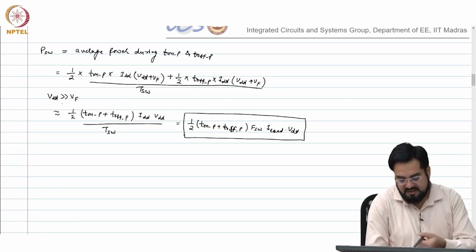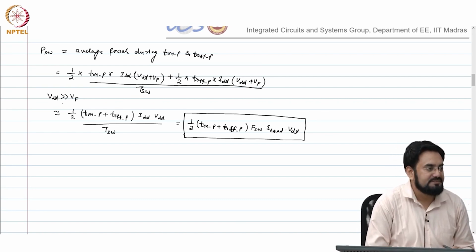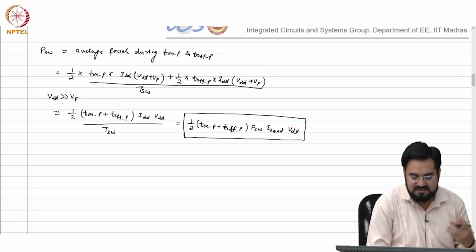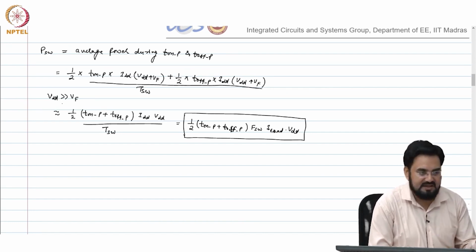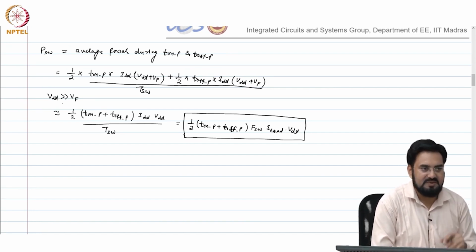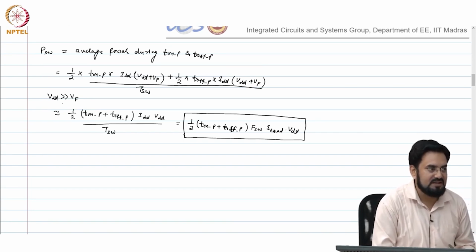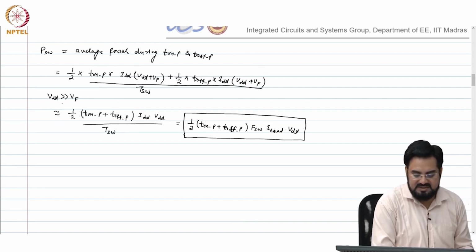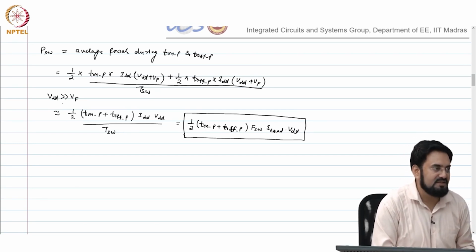So, all the switching losses, which is your dead time, your gate driver and this particular one, they will start dominating when FSW is very high. Okay. Some of them are a function of load and some of them are not, like your gate driver switching losses, but they all are a function of your switching frequency. So, that is why most of the DC-DC converters or switching regulators you find in the market, maximum available today might be 10 megahertz or so, and the current would be up to 1 amp, not more than that at 10 megahertz. But if you are looking at a 10 amp kind of a current, you will see achieving even 1 megahertz is not easy, because these losses are very dominant and they will kill your efficiency.